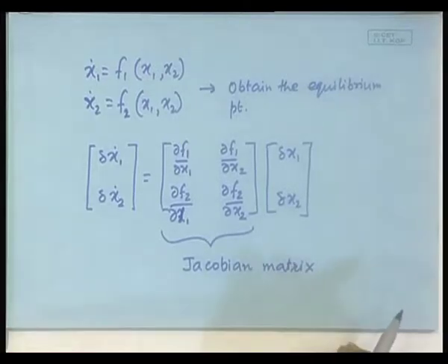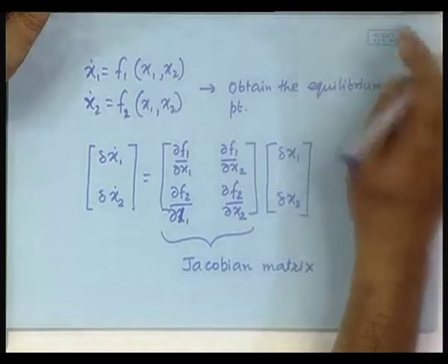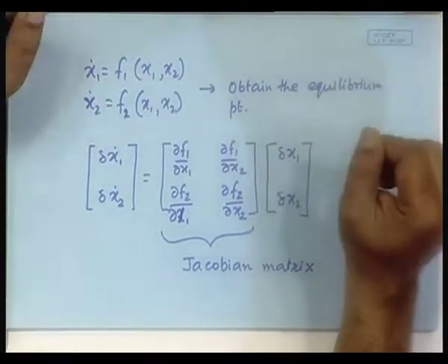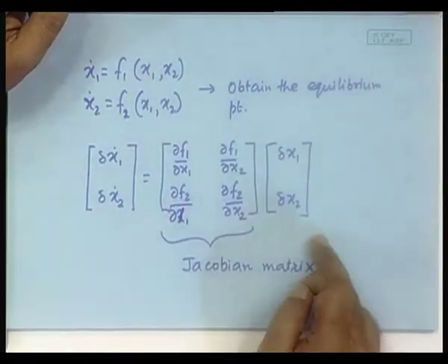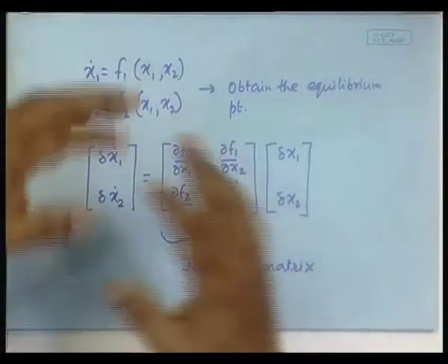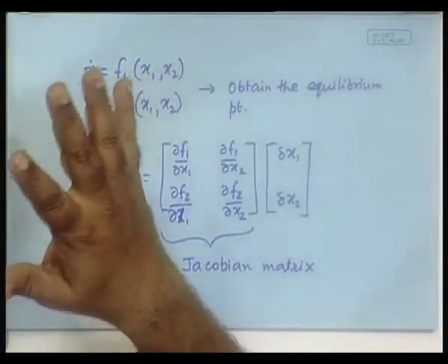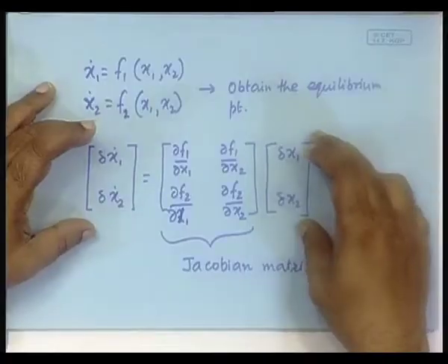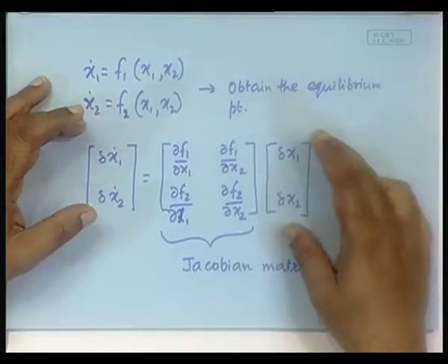Now, often in most studies in engineering, we only consider this equation. Why? The reason is that when we did the whole gamut of obtaining differential equations, you have found that 80% of the cases you obtain nonlinear differential equations. Even the simple pendulum is a nonlinear differential equation. But then we mostly study this kind of equations because most engineering systems are designed to operate at an equilibrium point, and the deviations from the equilibrium point are generally small.